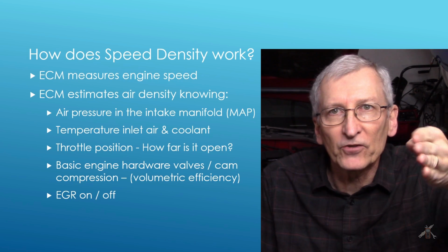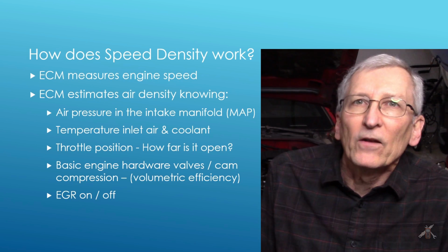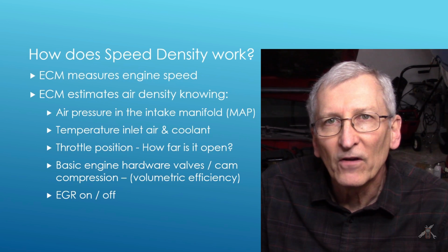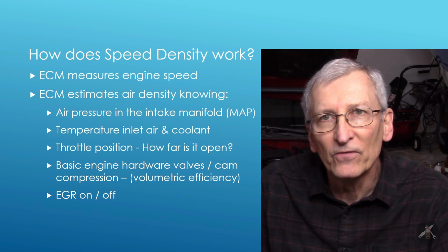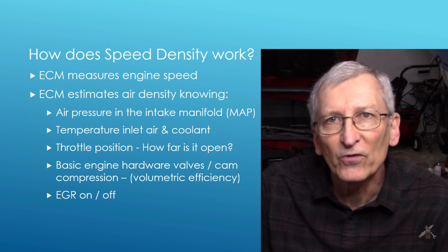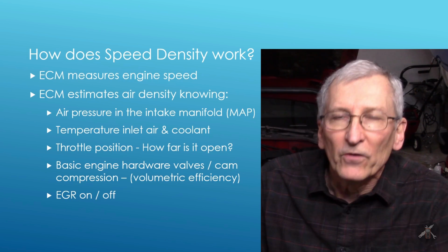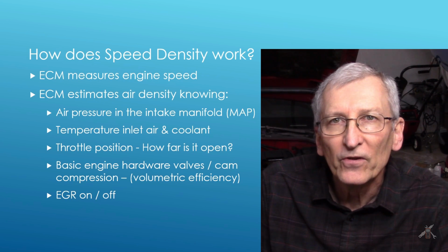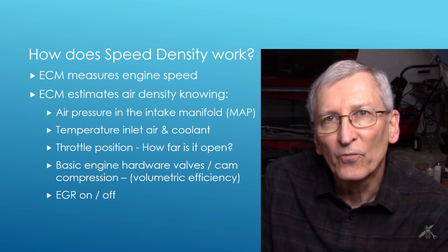It's sort of like a fraction that you're flipping upside down. Atmosphere is 14.7 psi, give or take a few hairs depending on your altitude and barometric pressure. So you work from that reference point with absolute pressure. Vacuum is how much that absolute pressure is below atmosphere.